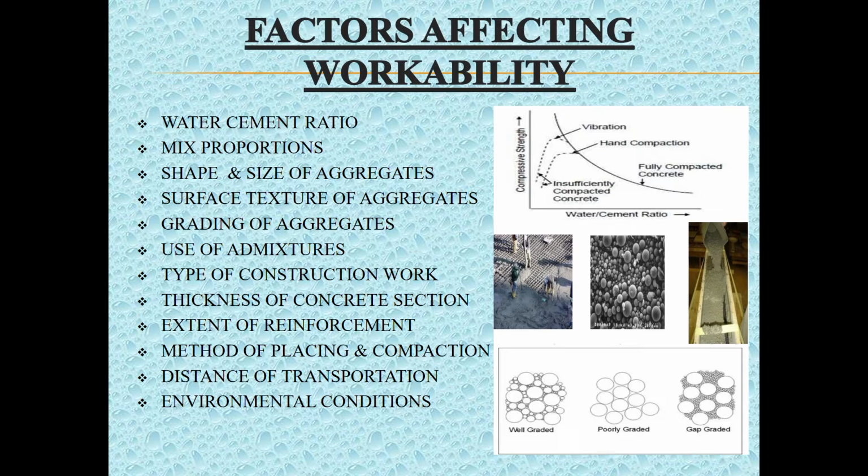Aggregate cement ratio is also an important factor affecting workability. Greater the aggregate cement ratio, the leaner is the concrete. Leaner concrete provides much less paste for lubrication per unit surface area of aggregates, which restrains the mobility. In rich concrete with low aggregate cement ratio, more paste is available to make the mix cohesive and fatty to give better workability.